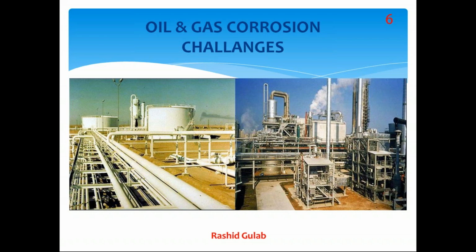The external factors that cause metal to corrode are water, acids, bases, salts, oils, and other solid and liquid chemicals. Metals also corrode when exposed to gaseous materials like acid vapors, ammonia gases, and sulfur, etc. Some materials are resistant to corrosion while some are prone to corrosion. When the material is prone to corrosion, we can prevent it by providing a good sound coating. This includes painting, plating, galvanizing. By all these things we can protect this steel structure.